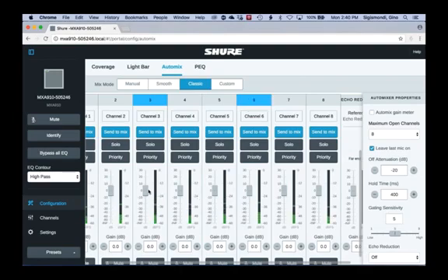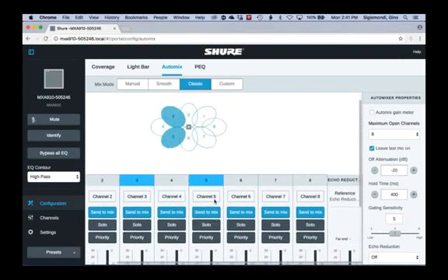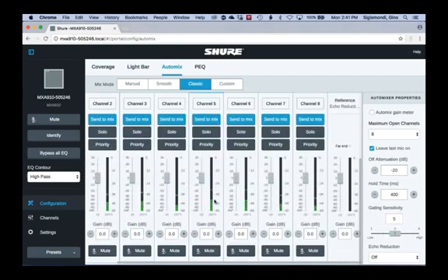And these are great tools to have now, because if you have a talker that maybe is a little quiet, you want to turn them up just to give them more level. If you turn up the gain before the automatic mixer, you're actually giving priority to that channel, and they're going to always gate on, maybe even if they're not talking. But now having the gain control after the mixer or post gating, you can now adjust volume levels without changing your gating decision.